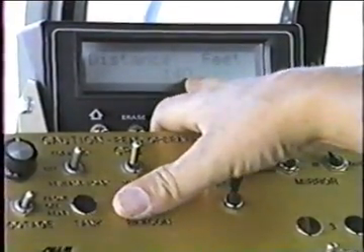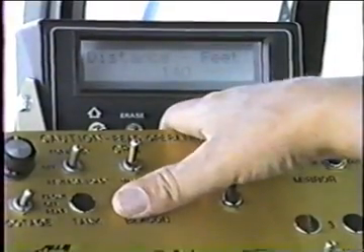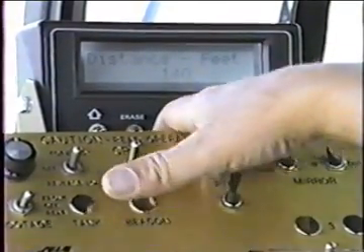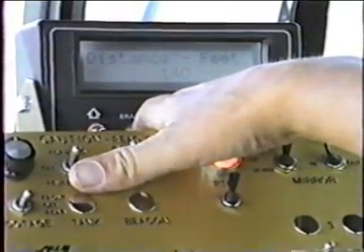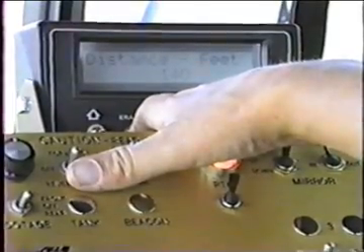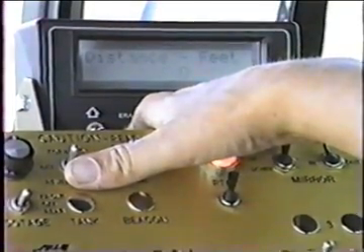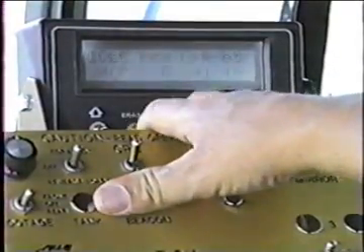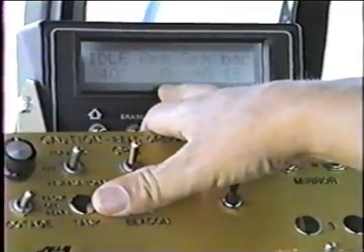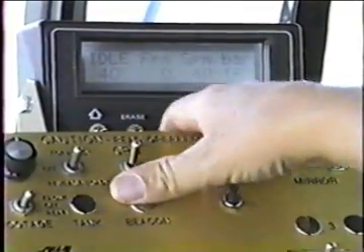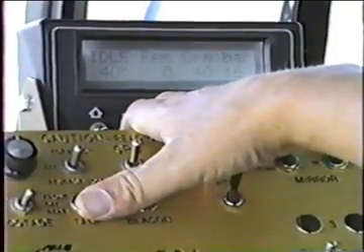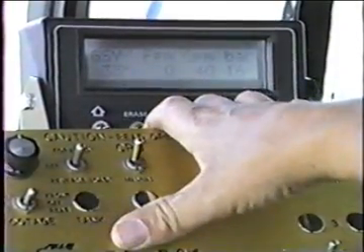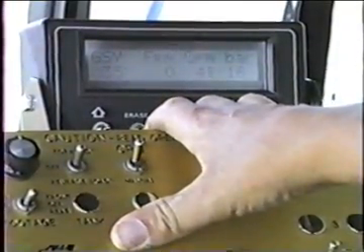Third thing is the distance traveled. This is showing 140 feet. If we push the center switch up to erase and hold it, it'll zero that number. Anytime we start a shot, we want to zero the number. Select again. Now we're back to FPM, GPM, and bar width. Holding it up to the erase position will put you back on GSY, gallons per square yard.